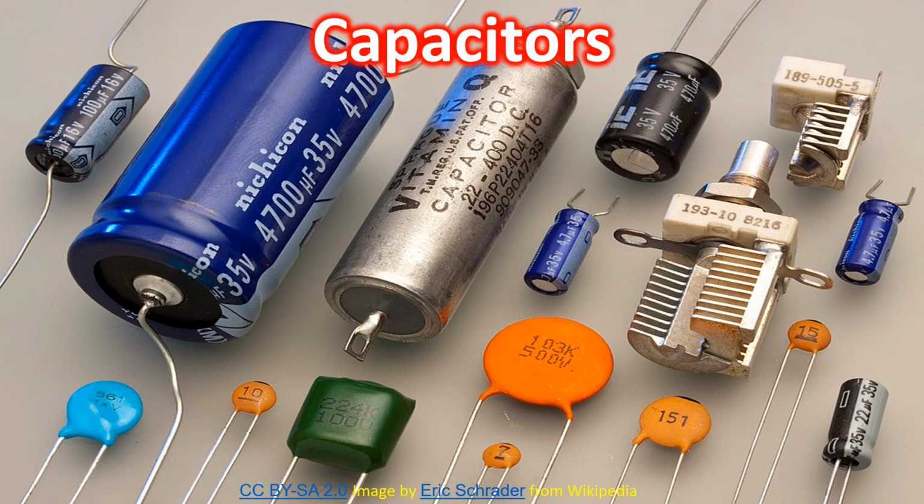There are also capacitors in which the capacitance can be varied, known as variable capacitors, often used in tuning resonant circuits. Capacitance is measured in farads, microfarads, nanofarads, or picofarads, depending on the value from higher to lower. High capacitance in circuits for smoothing out ripples in rectified direct current uses several thousand microfarads. Farad being a large unit is seldom used. A typical tuning capacitor in radios may be rated at 500 picofarads, 500 pF.